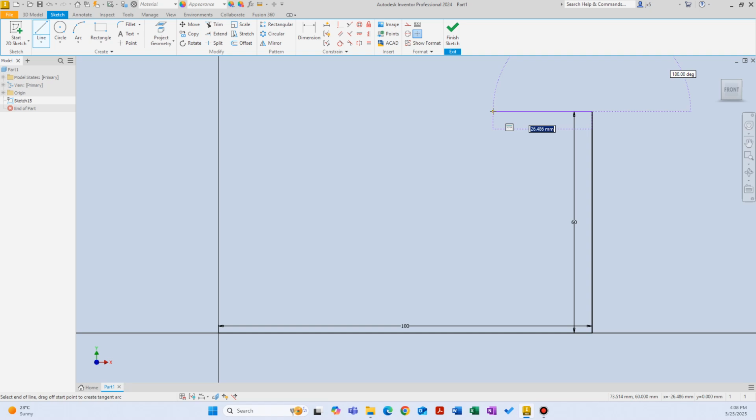I think it was the sketch constraints 7th video in the tutorial series. But I can come to the middle point of the first line and see that a dotted line appears. That means that this point is the middle point of the first line. Inventor is helping you to find these reference points and geometries to save time for you and make you more efficient and more productive.